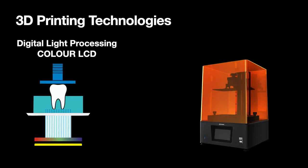So we are seeing a lot of people move to the digital light processing system. The basic one here is the color LCD, where the light source gives out light across different spectrums. And by the use of filters, the other spectrums are reduced, only the UV spectrum is used. And another set of filters creates an image of what needs to be produced layer on layer. Now, these filters act very similar to what we did in childhood, where we used our fingers to create shadows on the wall in front of a light source. So these filters act as creating the image layer by layer.